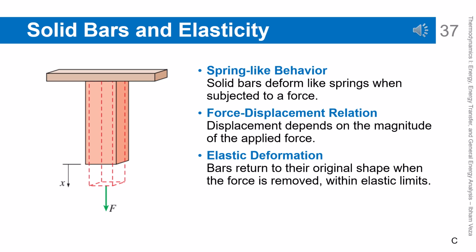Solid bars can also behave like springs when subjected to a force. The deformation depends on the magnitude of the force and the material properties. As long as it is within the elastic limit, the bar will return to its original shape. This concept is important in strength of materials analysis. Elastic energy can be stored in this deformation.